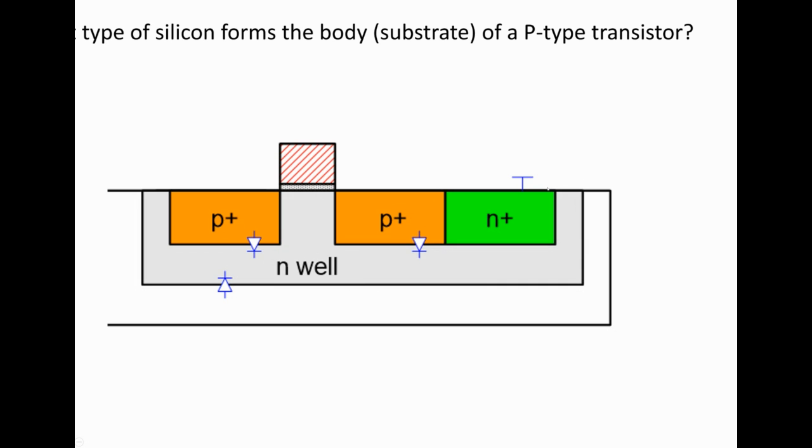Which is shown over here, this N-type. This is just a contact. Basically, it contacts VDD, and it allows a path for a connection between VDD, which ultimately would be a metal rail or metal wire, and that would connect through this diffusion area, and it would electrically connect the N well to VDD. And since that would be a high voltage, you wouldn't have any current going from the well into the diffusion. The only way you could have current flow, because current flows from higher voltage to lower voltage, and since the N well is the higher voltage,